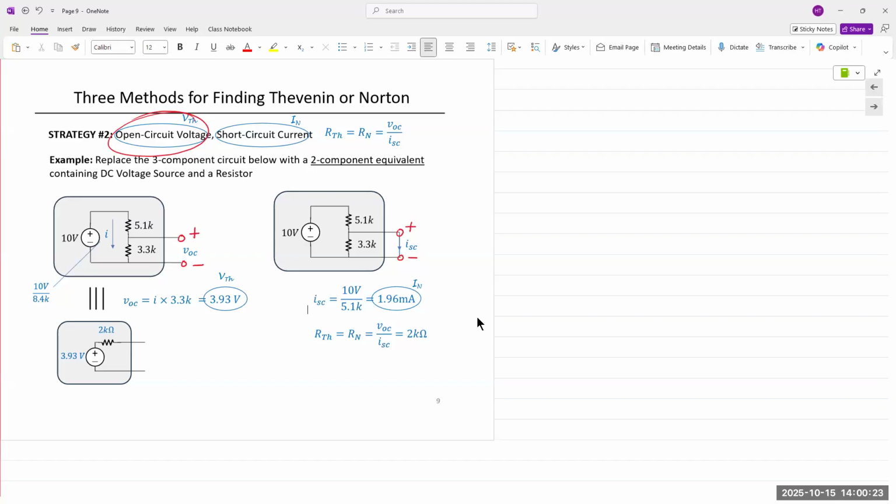So theoretical analysis is actually going to take longer because in theoretical analysis, we want to calculate what that voltage would be between those pair of terminals. We keep it open and we measure it. For Norton current, we have to short the terminals, because current needs a pathway to flow. So when you place a short, the current runs through that short circuit. So it's known as short circuit current, ISC, and that current is the Norton current.